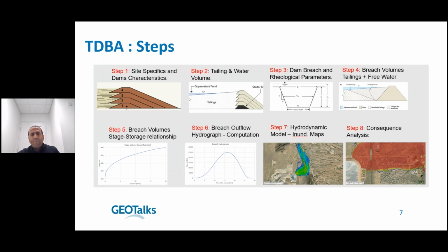Next is calculation of tailings and water volume, and depending on the characteristics of the tailings dam, even the volume of the tailings. And having these volumes, next step is to calculate breach parameters and also rheological parameters of the tailings dam.